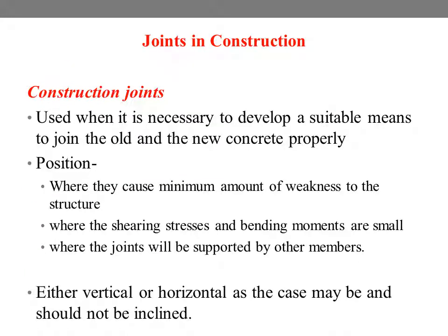Moving on to the next topic, that is joints in construction. The first one being construction joints. As it is not generally possible to place concrete in one operation, it is necessary to develop a suitable means to join the old and new concrete properly.